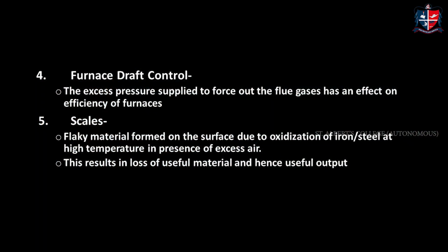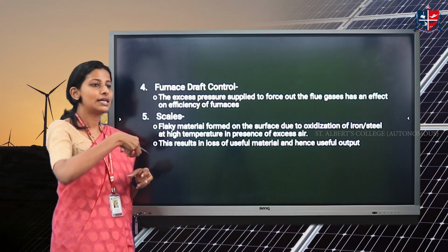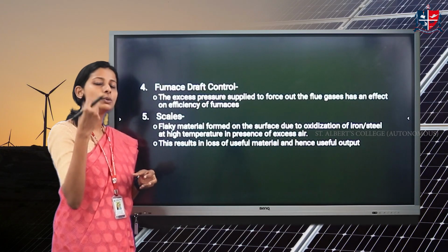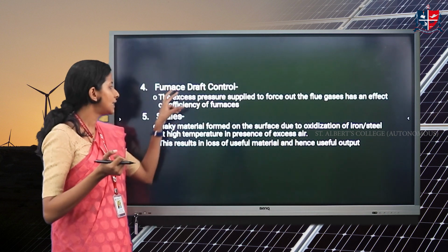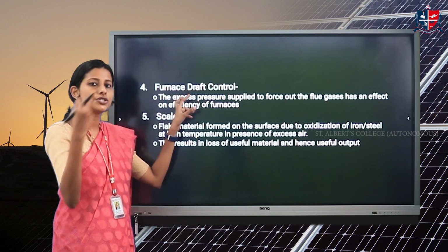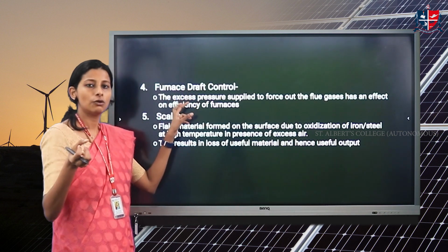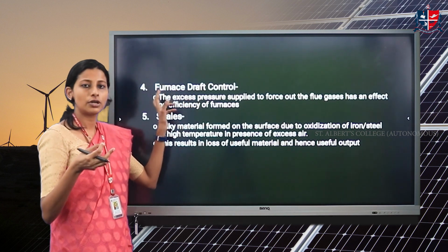Then there is draft control. The smoke and flue gases have to be taken out of the furnace, right? So that is pressurized out or taken out with the help of exhaust fans or pumps. That has to be properly controlled. The required quantity of flue gas has to be taken out properly, so that is another important parameter.